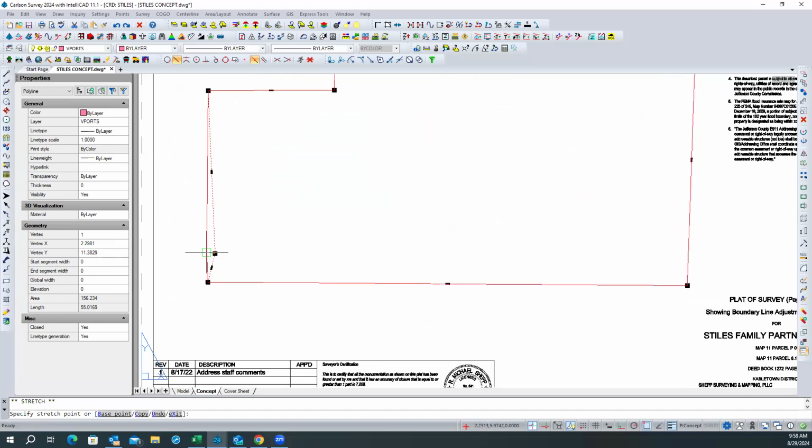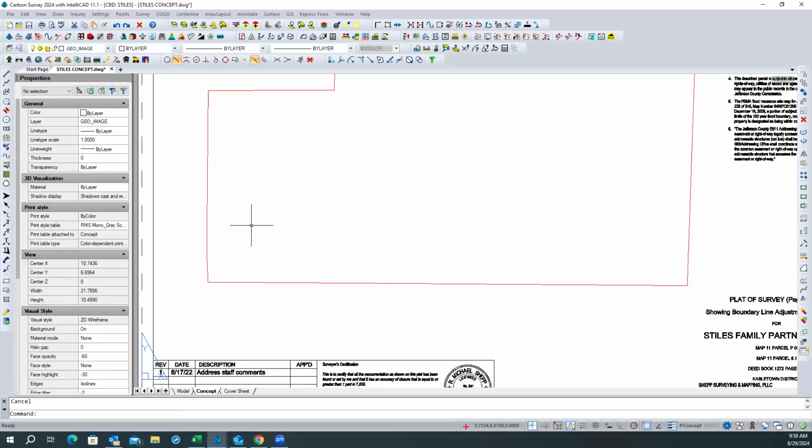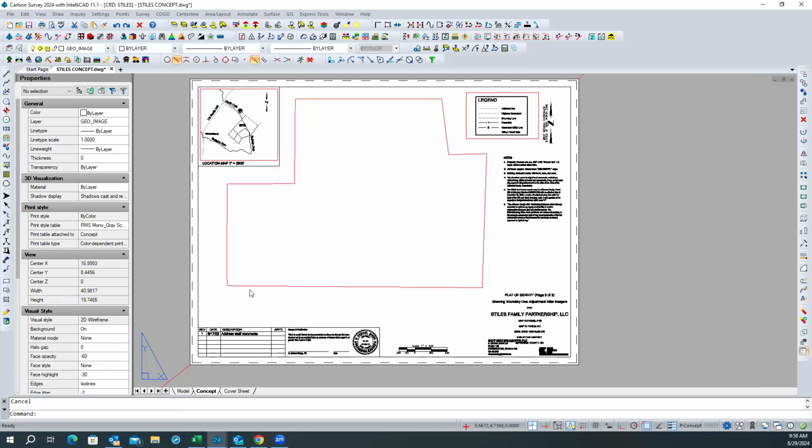And apparently that's where it starts and stops. All right, so that's going to be my viewport. So I'm going to say viewport, and I'm going to say poly, E for entity, and it's the one I'm going to want. All right, so now we got a viewport.